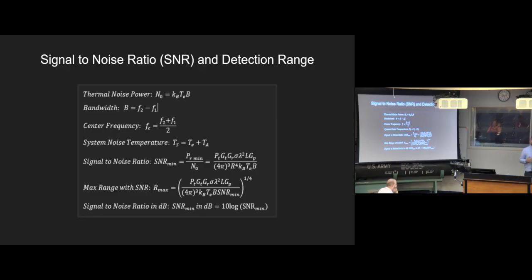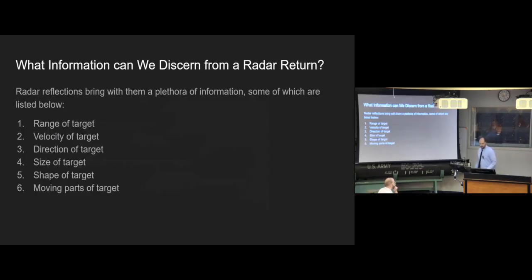Whenever you're going to be talking signals and stuff like that, the most agreed upon unit is decibels. So in this case, we like to convert signal to noise ratio into decibels, and the way you do that is you take the SNR that you calculate and just run it through 10 log, and now you're in decibels. Standard 10 log scale. Alrighty.